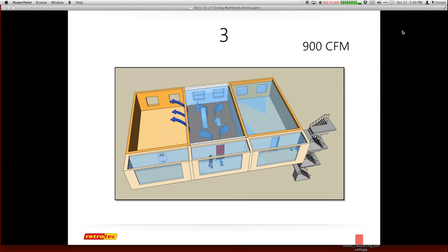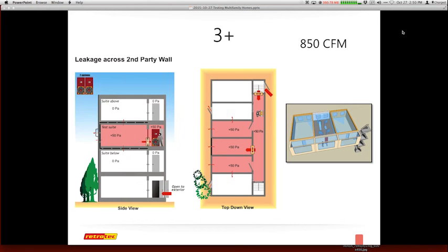And here's a 3D illustration showing that setup. Again, the door's open on the right. The pressure's gone into the room on the right. I no longer have any leakage over there. I could have some in the interstitial wall, but I have nothing that's going into that unit itself. And if your units are small enough and you have a good seal in your hallway, I can open the door on the other side of the unit and now actually have pressure on both sides of my central Unit B that I'm testing, and it only went down 50 CFM to the unit on the left. So I know that there's not a lot of connections between the unit on the left. And here's our 3D illustration.